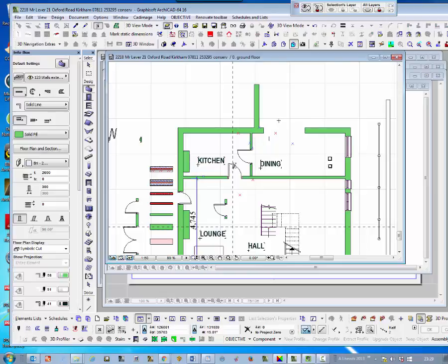Now again, from my survey notes, I know that isn't an external wall in this case, but I'm going to use that, and I'm going to make a copy of it from that position across to the other side of the room, and the other side of the room is 2960. So X 2960 plus equals, right, and like we say, it's shift clicked, we want to take this wall to the inside face of that, so reference lines should really join up with reference lines, so that's joined up.